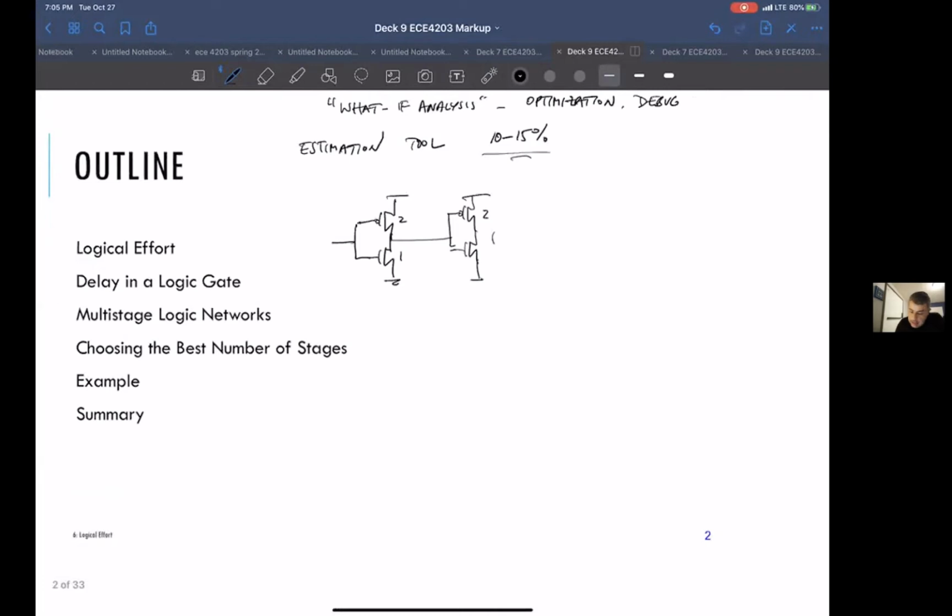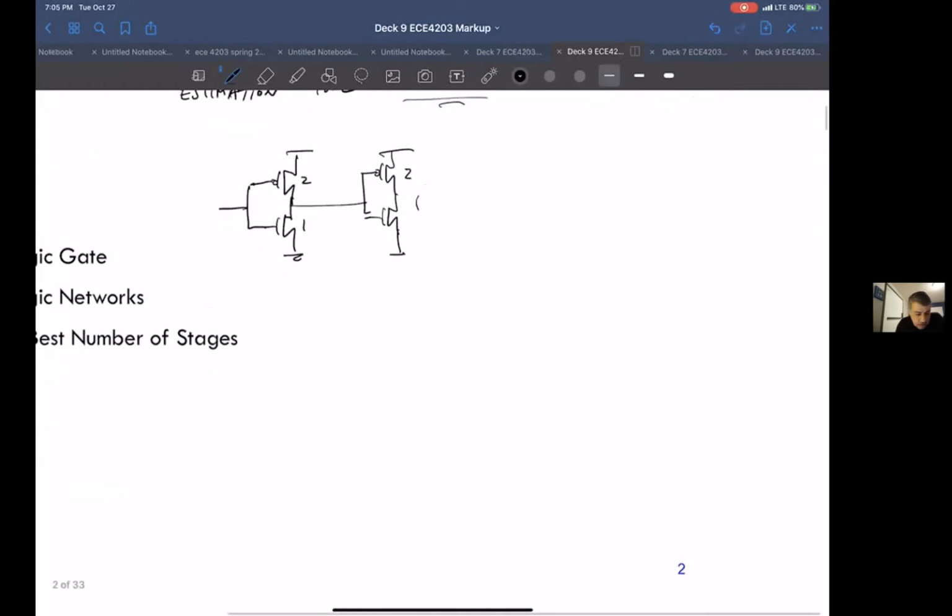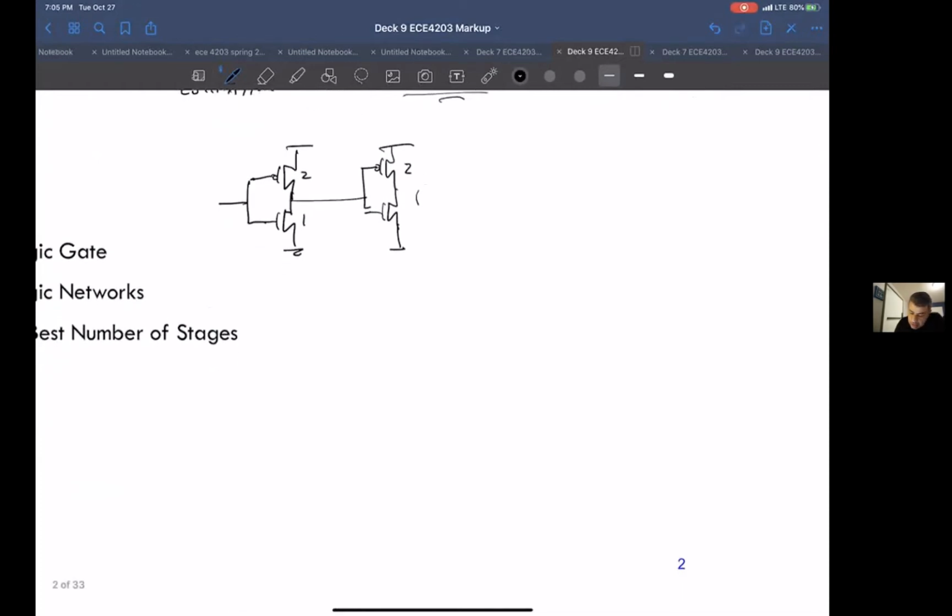And what we said was we would model the PMOSFET as a resistor with a switch, and the resistance of a unit element PMOS is 2R, but because we have twice the width of a nominal, I'm just going to make it 2R divided by 2. So that's the resistance of that guy.